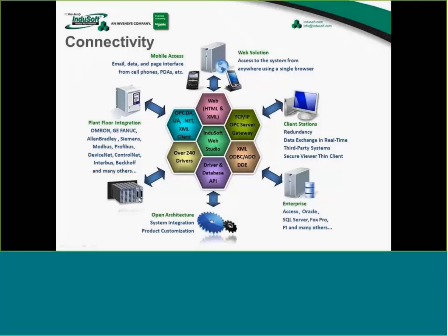One of the key points, and the reason I bring up this slide, is that with InduSoft Web Studio and the tags, the core of this, we can function as a gateway, a communications gateway from any of these devices to any of these other devices. So for example, if you wanted to get information from an Omron PLC into a database, you can use InduSoft Web Studio to do that, or from OPC into a PLC, or you can even do this from one brand of PLC to another brand of PLC. So we let you do that and encourage that.